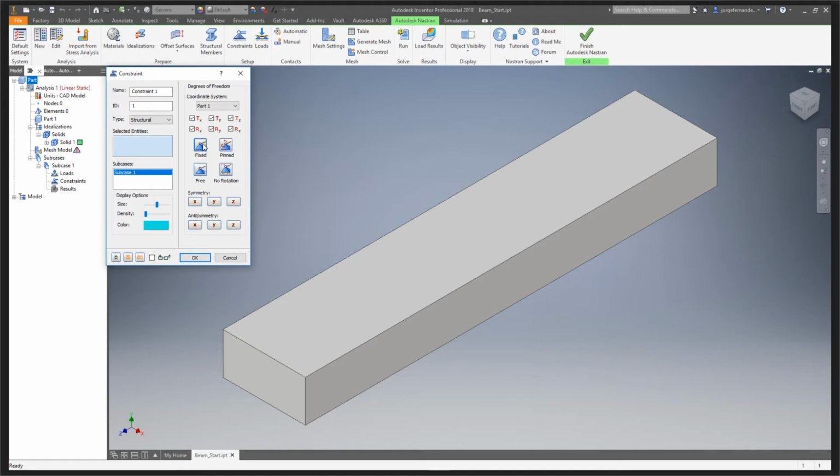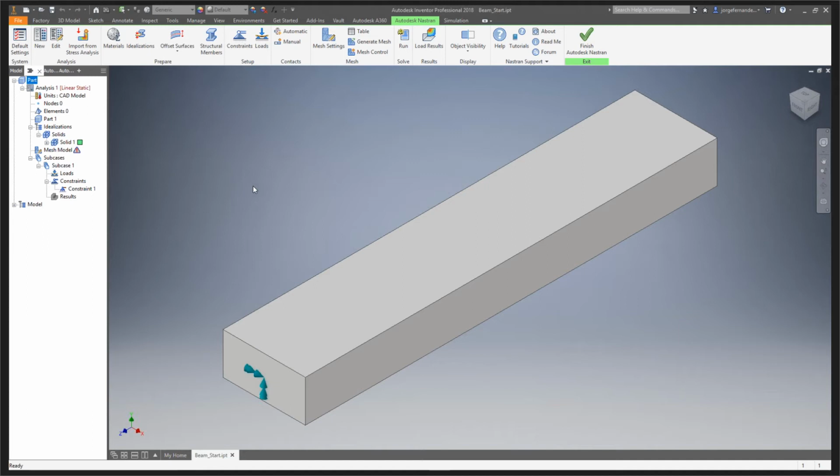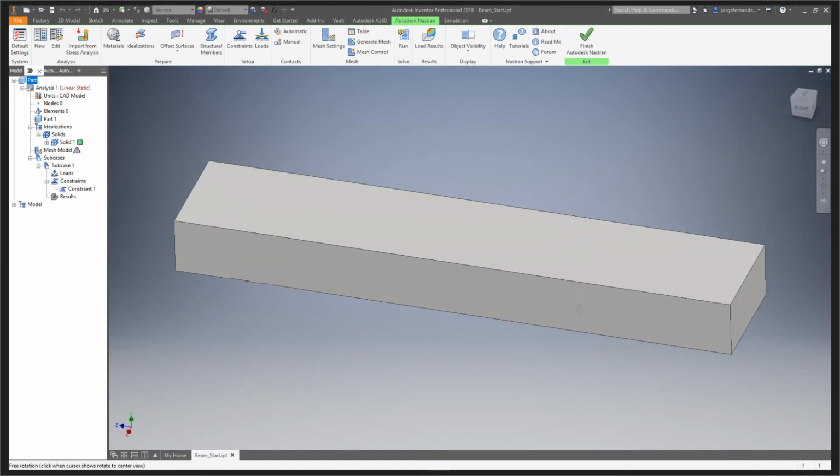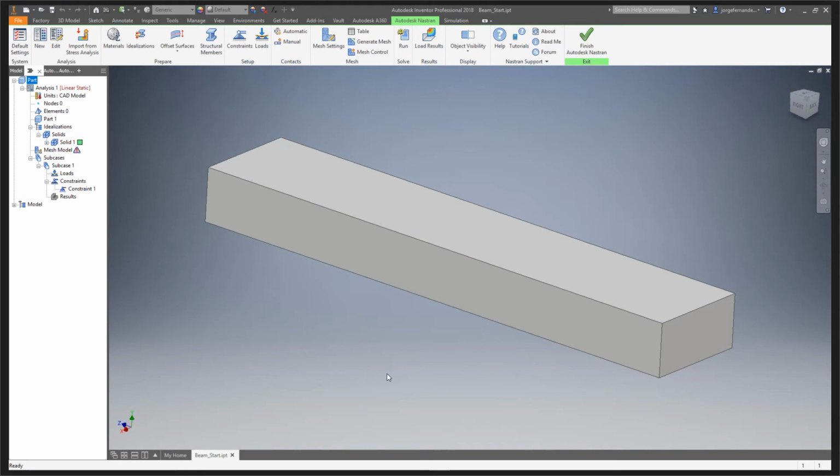In this case, we want to completely fix according to this face here. Yep, and as you can see there, you can manually select the degrees of freedom up there. Above the cute little pictures, there's 6 boxes for checks. And if you have a very particular way that your product moves, or is predicted to move, you can go ahead and set constraints that way as well. Exactly.